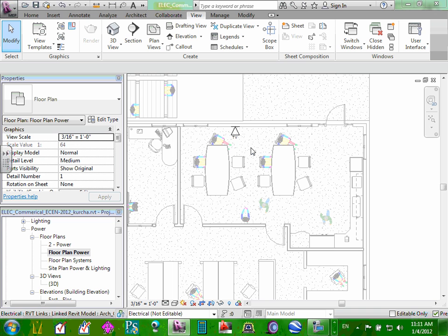I have lunchroom 119, 1 receptacle per wall. Everybody know what I'm reading from here? Circle page 9, so I'm going to read them. They want 1 receptacle per wall first. Lunchroom receptacle, 1 receptacle per wall. It's a standard. Lunchroom coffee pot, they want 1 receptacle GFCI. Can you guys see that?